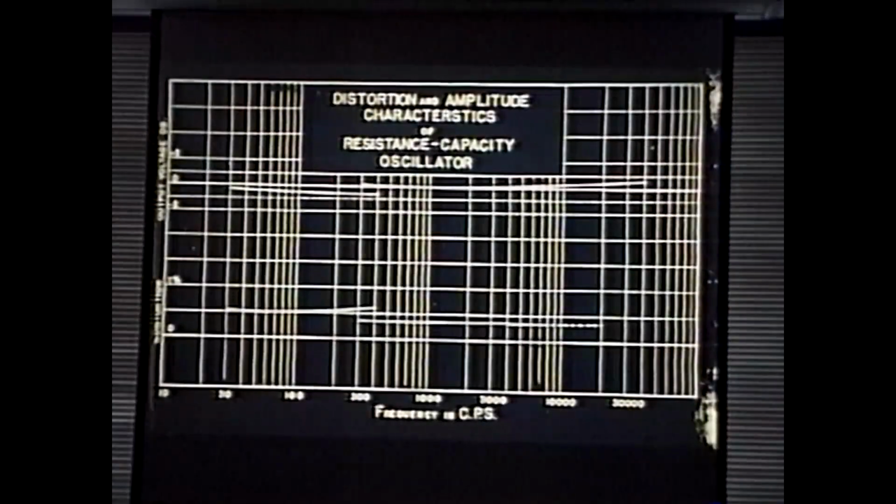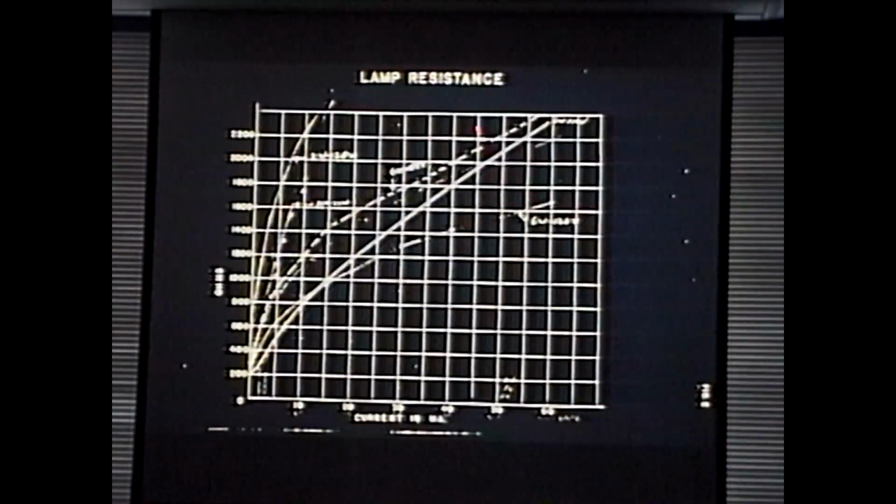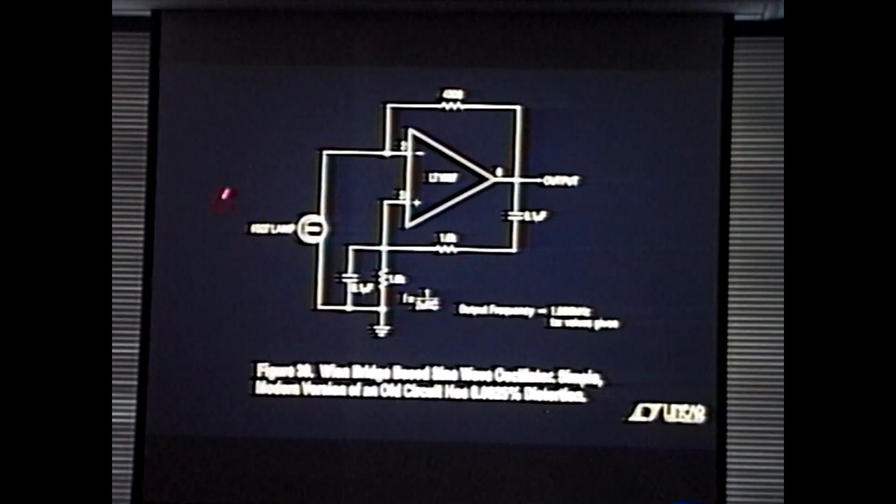I was too lazy to plot these characteristics. I just lined up a dozen lamps and started screwing lamps into this circuit until it did anything at all, and then played around with this value. That's the lazy man's way to find the right lamp, to get the right VI characteristic. If you build this circuit and you just plain turn it on, luckily enough the lamp that won the Derby was a 327, which is a very, very common aircraft lamp. It's the most common 28 volt, 40 milliamp aircraft lamp. That's easy to get. If you just screw that circuit together and build it, you get very low distortion.